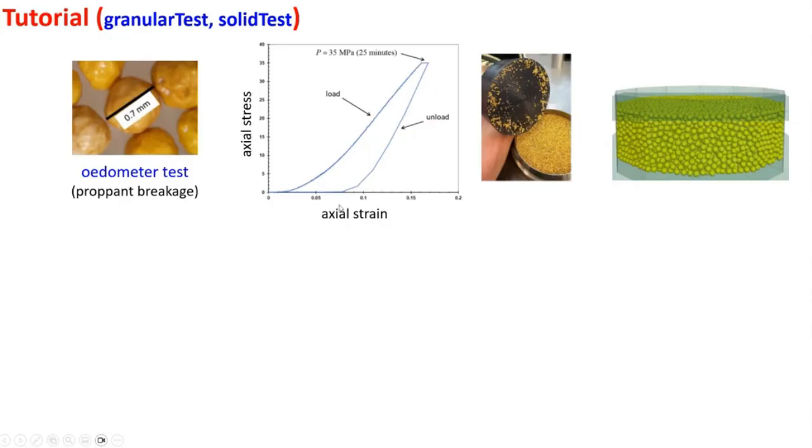Yes, exactly. If you look at this curve, I'm going up and I get to here. If I draw a vertical line, the area under this curve is the energy stored in the system. It's the work done on the material. And if there was no time dependency and nothing changed, it would go down the same way. So the work done loading would be equal to the work recovered when I unloaded.